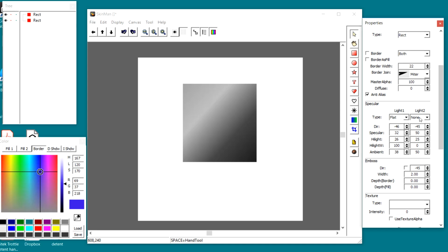And then let's look at the same thing with a spherical, and you can see that gives us a spherical, and we can change the width of that too. Here I'm going to change it by dragging that down. For some objects that are round, this is quite effective. Not so great on a square object because the corners show, but for a round, three-dimensional object, where you want it to look like a ball or something protruding out, that's perfect. Or you can go negative and make it look like an indentation.